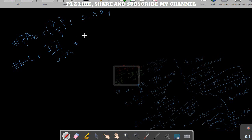Here I got 5.48, which is rounded to 6. Remember, you can't choose 5 bars, right? So we have to add 1, so that's why I'm choosing 6 bars. So here this selection is also close, and here this selection is also close. So here I need 8 number 6 bar, and here I need 6 number 7 bar, right?